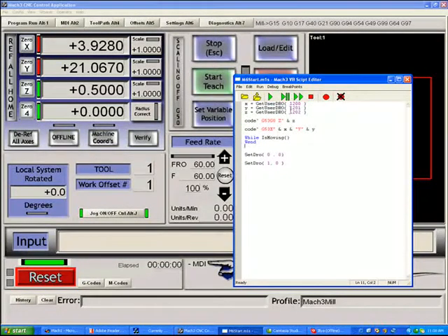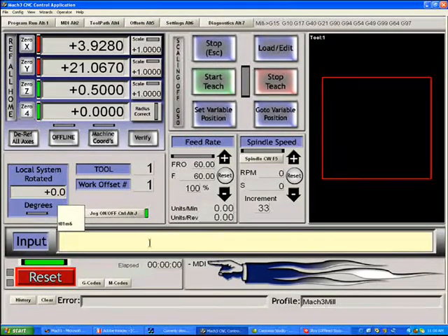So now this script is going to read the tool change location, execute the commands for movement, wait while it is moving, and then 0 the X and Y. Let's save this by just pressing this Save button, and we can exit the scripter. Let's try this again. T01 M6. Now you see what happened. Now it moved to the correct location. In machine coordinates, we're at 10, 10, 0. And in work coordinates, we zeroed the X and Y axes and left the Z alone.